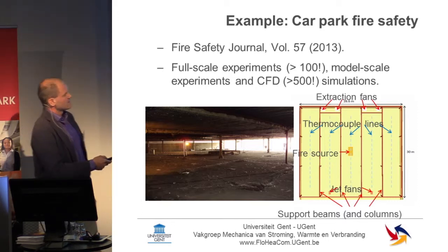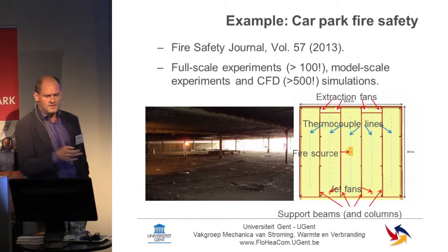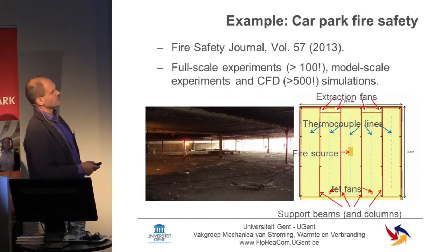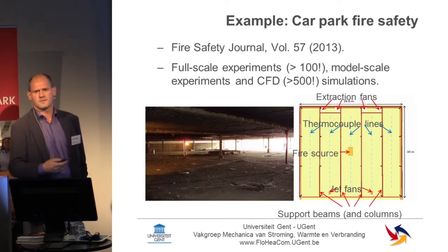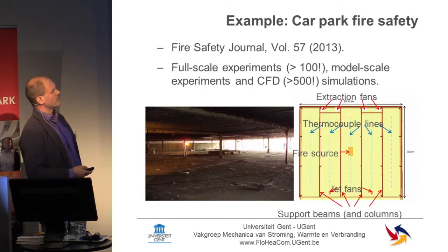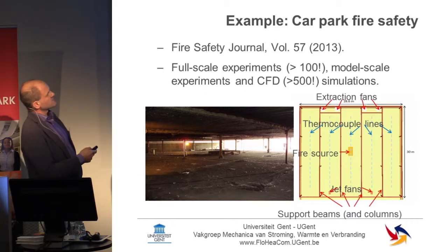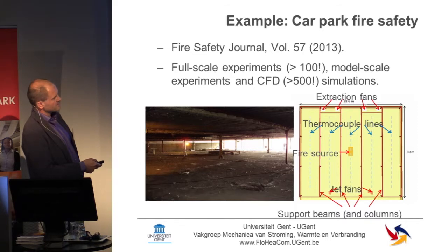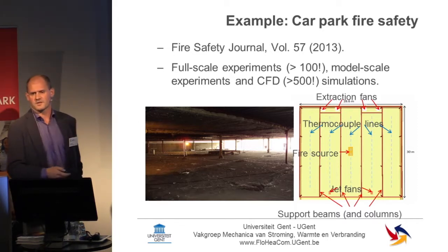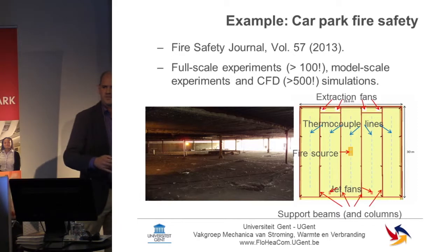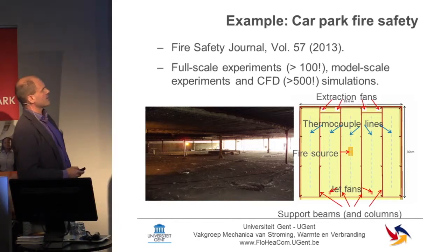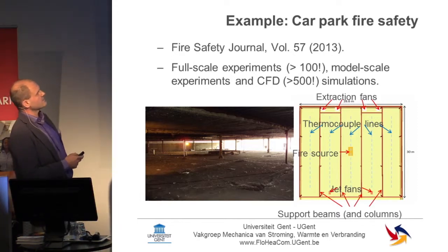And we set it up here. You see the picture on the right-hand side. You see the diagram in a parking garage of about 30 by 30 meters and 2.6 meters height. What we did is we regulated the extraction fans, how much smoke we extracted per time unit, and also the inlet. So here, in this picture, the inlet is entirely open. It's over here. And we could also close it in part. So that way we could look at flow patterns in the parking garage.